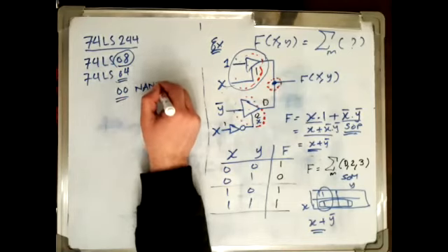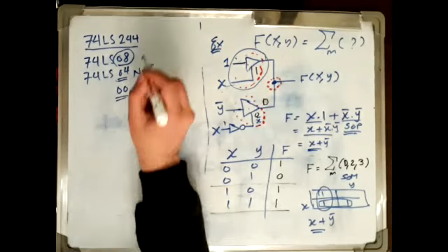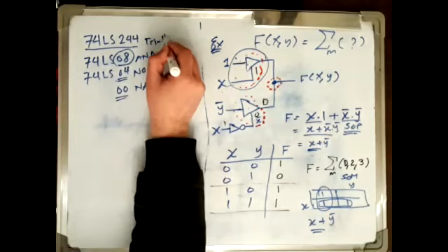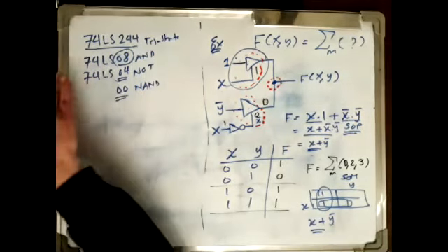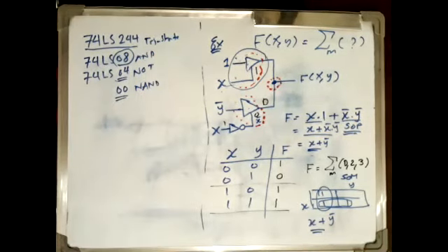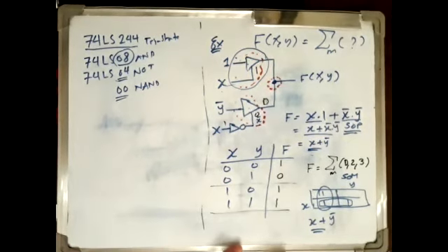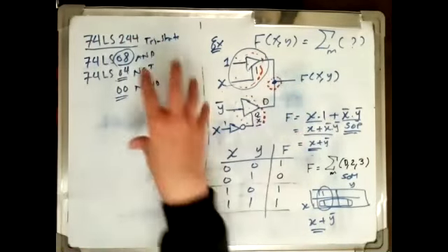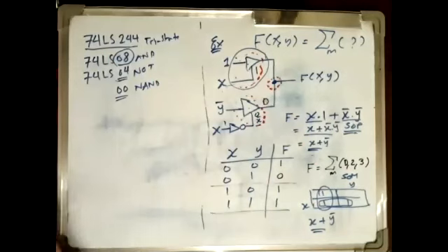It's an AND. This is a NOT. And this is an AND. Double check, and this is a tri-state buffer. So these are real things that you can buy and use to build logic functions. And those who will take the lab, I guess in the first 4 or 5 experiments, students work with real components. They design their function, then they bring these components, wire them up, and test their functions.